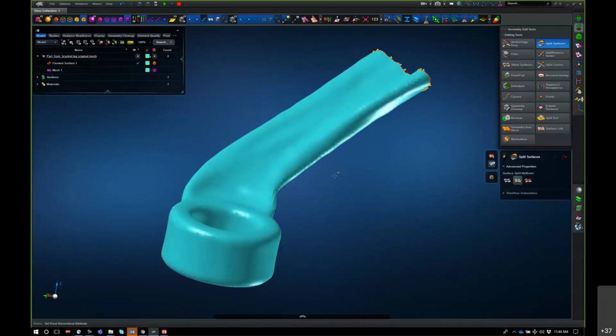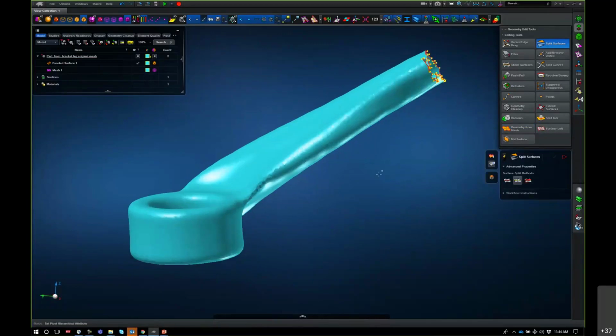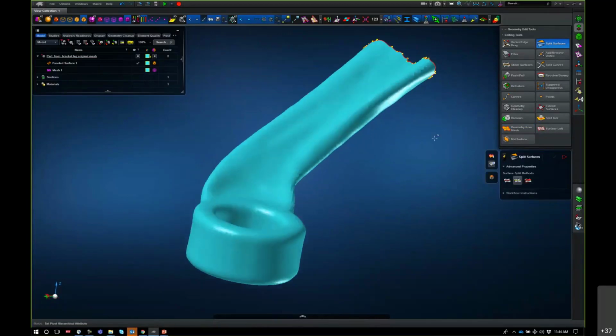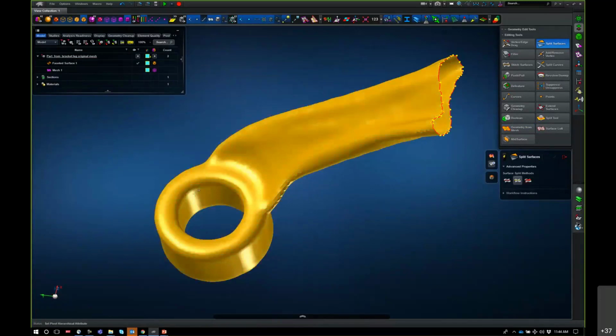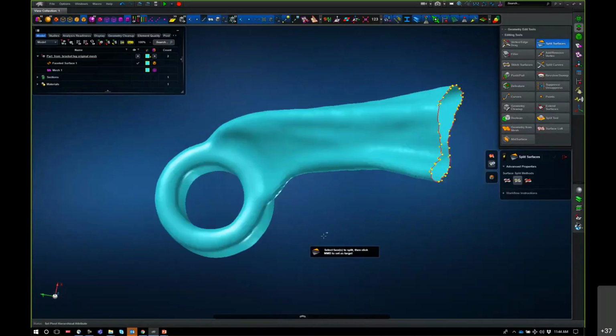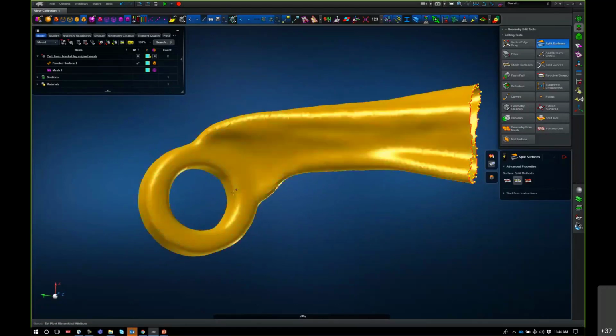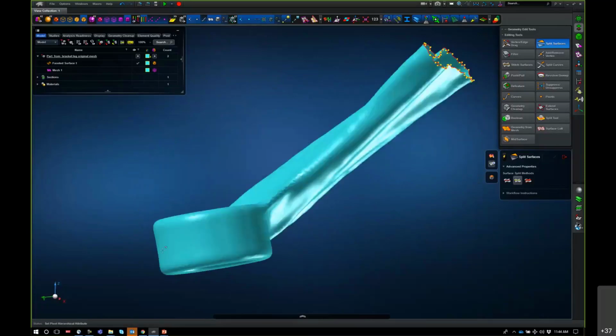And here's where it takes a little bit of skill. It's not as hard as hex meshing skill, but it takes some skill to understand what NURBS can do. What's the functionality of NURBS? So I have a cylinder here, for example. This is not a true cylinder. Smoothing is not going to work on this. So I have to split this up into at least 180 degrees, if not 90-degree sections here. Anything for the fillets, anything for the outside.